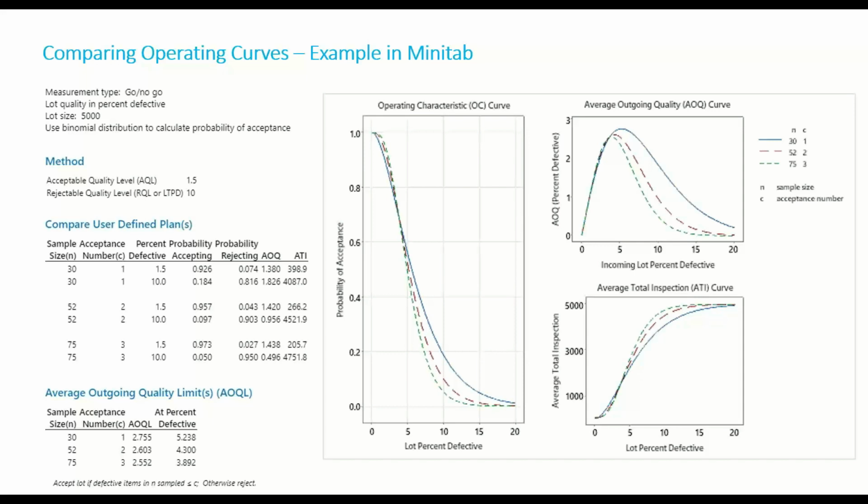But definitely, you pull a bigger sample and you're saying you're going to be looking at more, right? If you pull a smaller sample, you're not going to be looking as much, so it's a risk, definitely, to the consumer. Maybe not so much a risk to the producer because you're going to get away with more, right? I just pulled a sample of 25, and as long as I have maybe 3 defective or 2 defective, then, I'm pulling a smaller sample. So what are my chances of seeing the defectives that are in there? Less, right, less probability. If I pull a bigger sample, that's going to cost the producer more money, but it'll be more beneficial to the consumer because you're taking a better look.